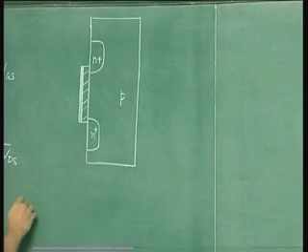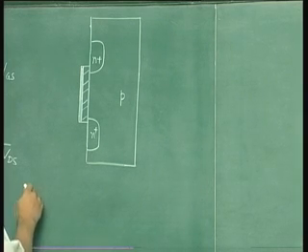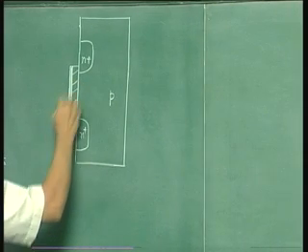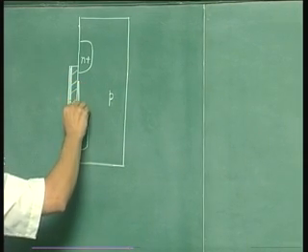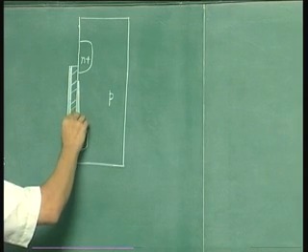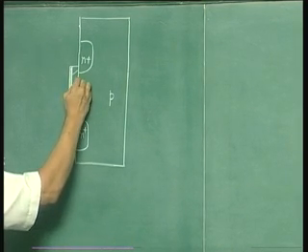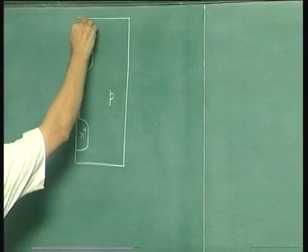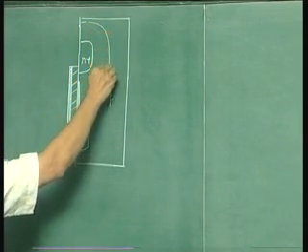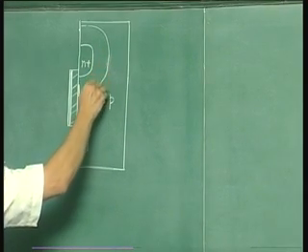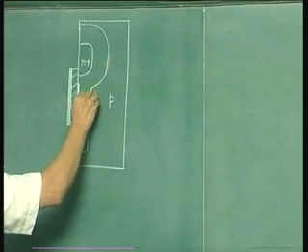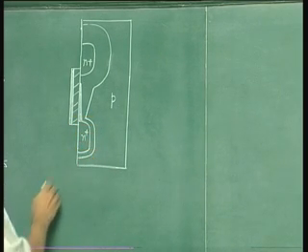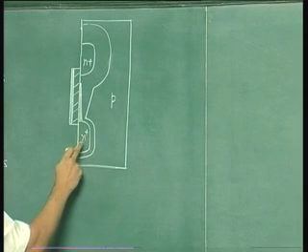Now if you show the depletion region and the inversion charge, it will look as follows. We are showing beyond saturation. So beyond saturation, the picture is something like this. This is the inversion charge decreasing from source to drain and becoming 0 here, and then you have the depletion layer coming like this. The depletion layer is smaller at the source because drain to bulk voltage is more than source to bulk voltage.